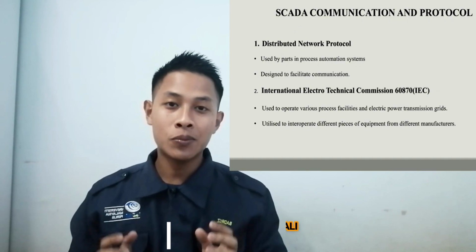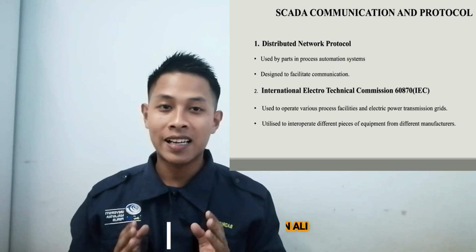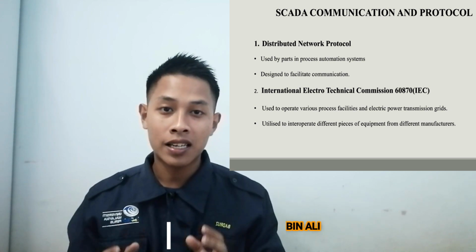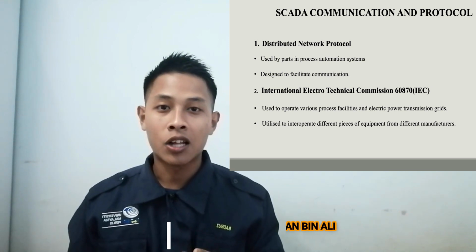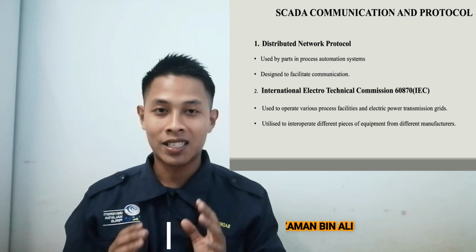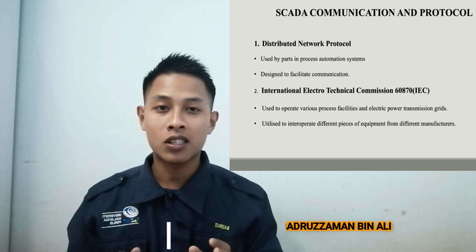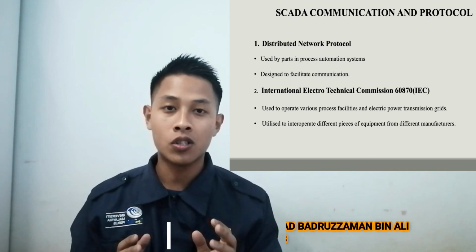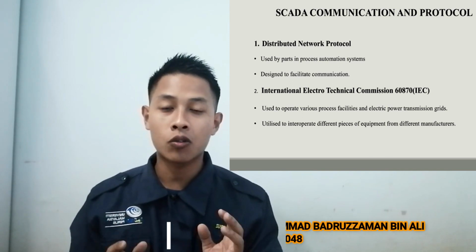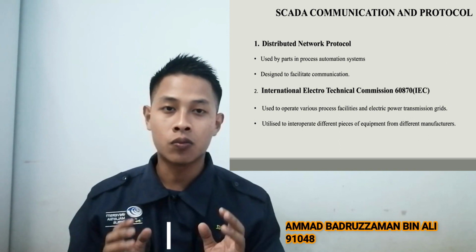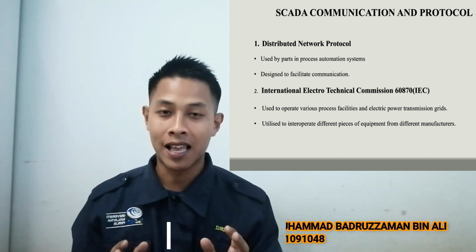Next part is SCADA Communication and Protocol. Distributed Network Protocol DNP3 and International Electrotechnical Commission are two categories which are significant to SCADA protocol. First, DNP3. DNP3 is a collection of communication protocols used by parts in process automation systems, such as those found in chemical and utility plants.